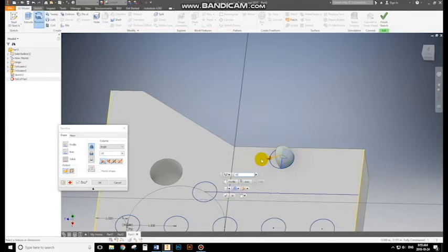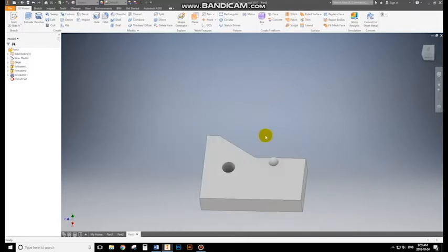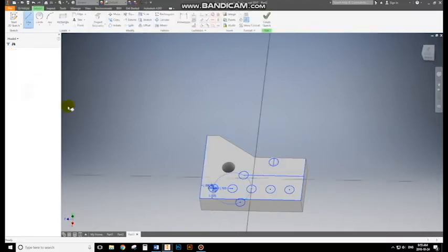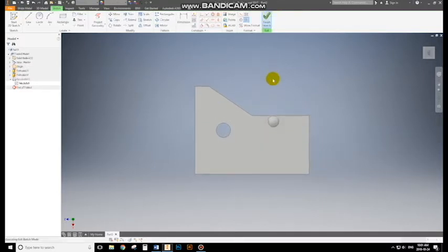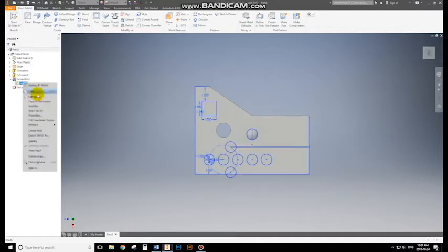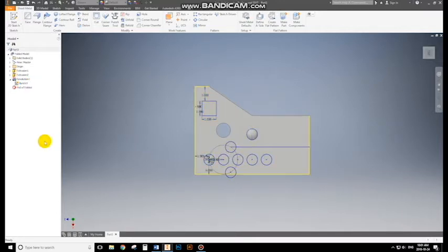After we extrude or revolve a sketch, the sketch disappears, but sometimes we want to go back and edit that sketch. In the browser menu on the side, we can see everything we did to make this shape. If we click the arrow beside the feature, the sketch we extruded appears in the browser. If we right-click that sketch, then click Edit Sketch, we can change the sketch. We can also click Visibility, and the sketch will reappear.